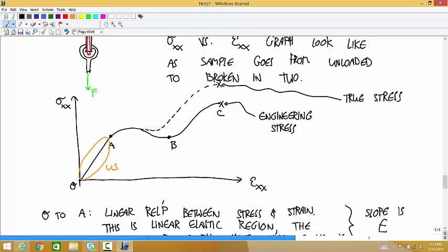Well, this is just looking at axial stresses and strains, and so the different shape of the bar would affect what kind of stresses and strains you have in the material for a certain kind of load, but this is applicable for the axial stress and axial strain no matter what the shape of the material is. This is just looking at a single point with a certain kind of stress. So yes.